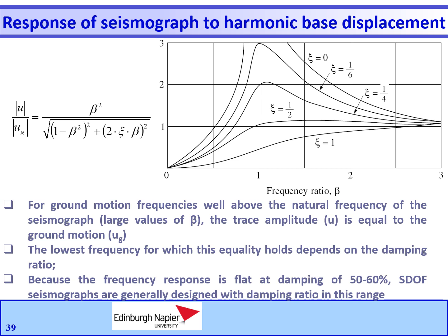This basic concept is clear, but to be achieved, we would need a transducer spring so flexible, or the transducer mass so large, or both, that the mass stays still while the support beneath it moves. Such an instrument is unwieldy because of the heavy mass and soft spring, and because it must accommodate the anticipated support displacement, which may be as large as around 1 meter during earthquakes.